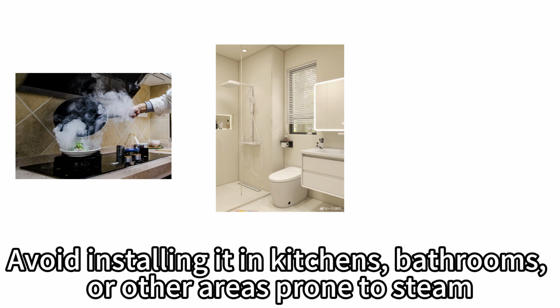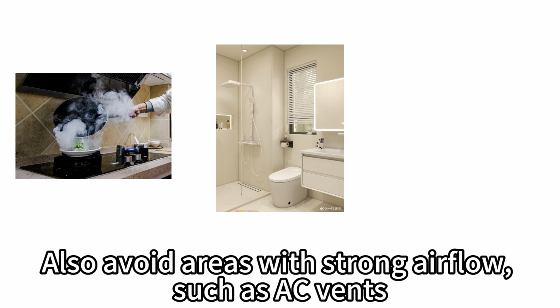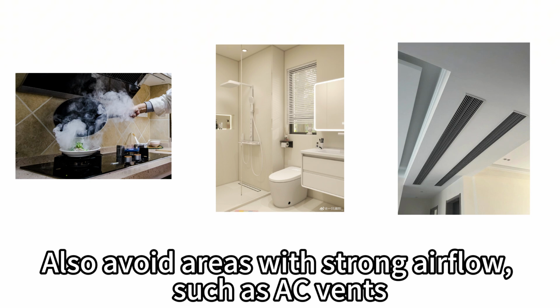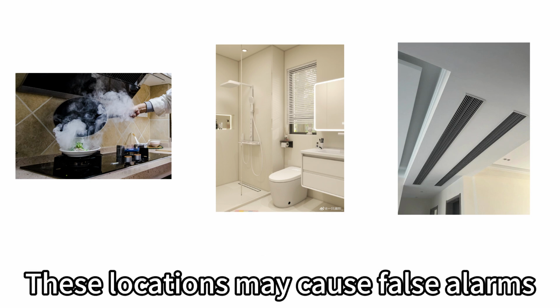Avoid installing it in kitchens, bathrooms, or other areas prone to steam. Also avoid areas with strong airflow, such as AC vents. These locations may cause false alarms.